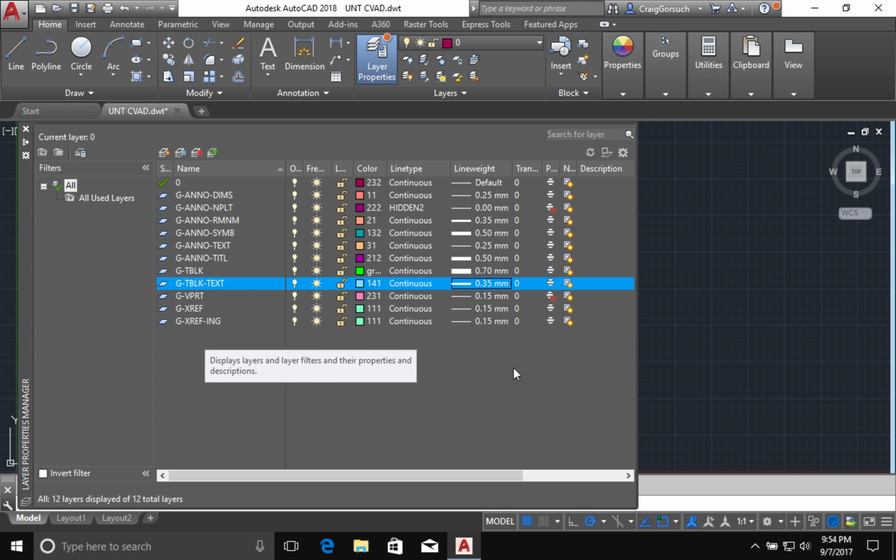There's another correction that needs to be made here. There's a line type in both of these sections that's listed as overhead. That's an internal line type that I use at work, and we're not using it here in class. So we're going to use hidden instead. And for the column grids, you'll see another line type that's listed as center line. We're going to change that to center 2. Again, hopefully it'll all make sense.